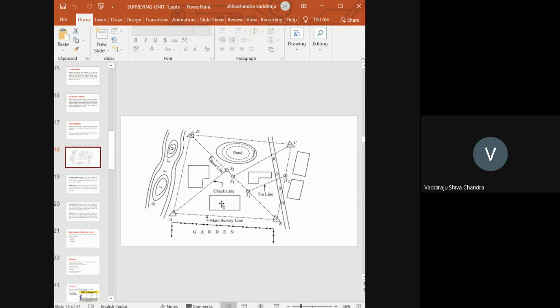Okay. So now I'm identifying S2 as my point, and I'm going to measure the distance of S2 from A. Or I will take S1 and measure the distance from C. Once I measure this distance, AS2 or CS1, I'll keep it as a record.